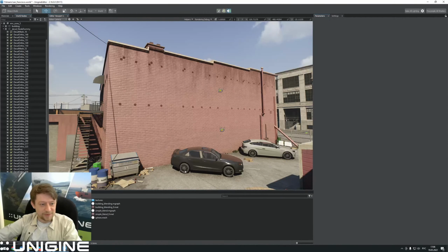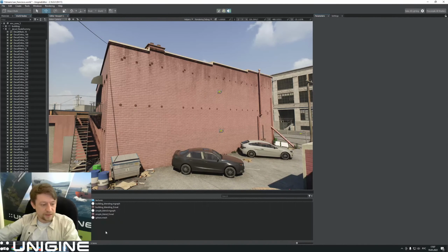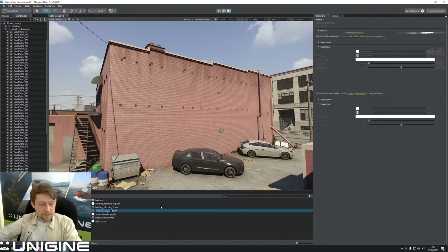let's get a little bit closer with material graph editor. So you can create a new material just by opening up the context menu inside the asset browser here. If you go to create material, you can see three options here. Inherit from base material is a legacy, and we have two options regarding material graph. So it's actually the graph itself and the subgraph. I will tell you a little bit later what the subgraph is. So right now, let's create a material graph.